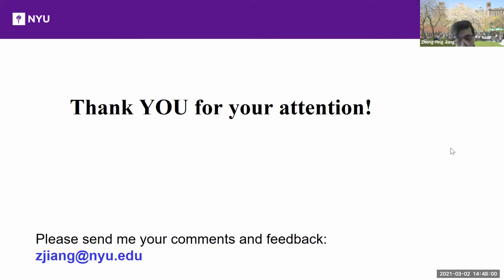Okay, so for one vehicle, we can use vision-based lidar control to control the motion, for example, to run at constant speed or to stay in the center of the lane. But for the string of vehicles, we assume that the motion of the leading vehicle is known. So the following vehicle will have the objective to maintain the minimal inter-vehicle distance to the preceding vehicles. We also want to guarantee that there is no instability phenomenon like string instability, which means that the disturbance from the leading vehicles is propagated through the string. That phenomenon should be avoided. Using autonomous vehicles, you should be able to dampen the propagation of noise or disturbance from leading vehicles.